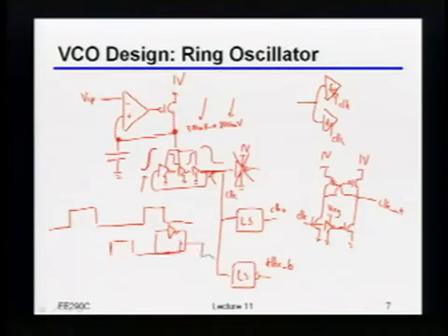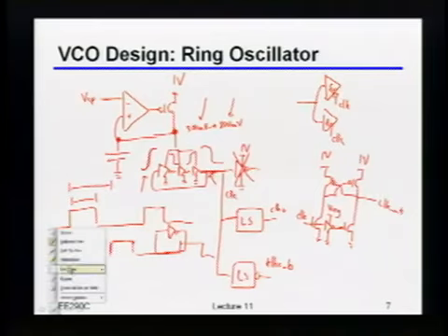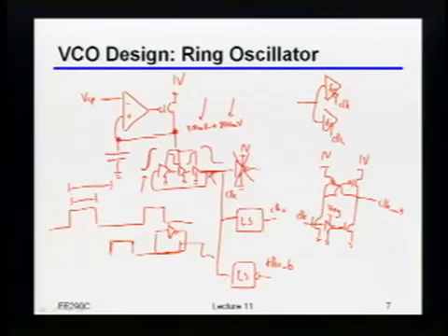So in other words, each individual duty cycle is still wrong, but the spacing between the two edges will be correct. Okay? And in this particular example that I've drawn here, having at least the spacing between the edges be correct is better than having both the bad duty cycle and the incorrect spacing. Does that make sense? Or more questions on this?